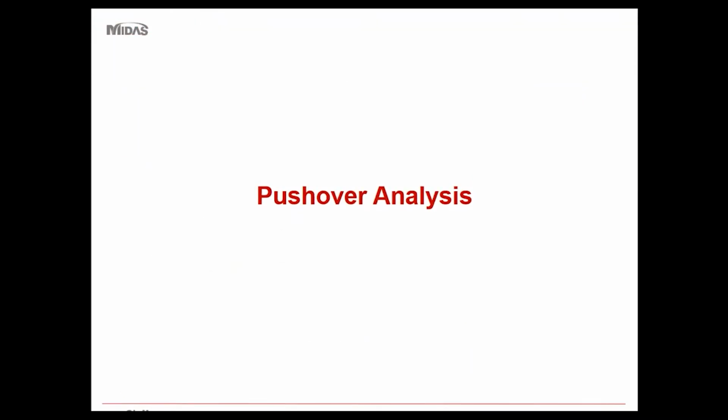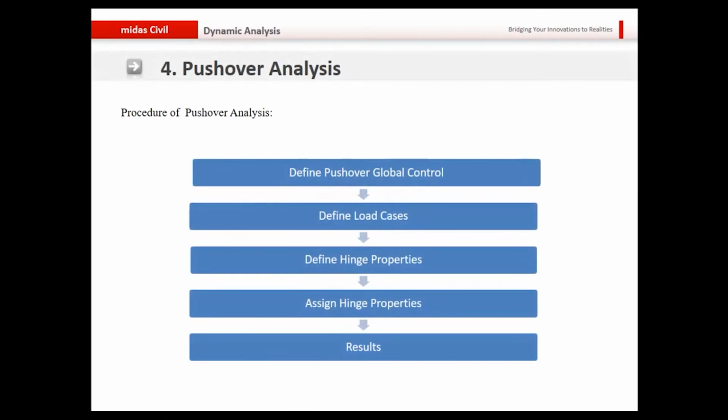Then in the program we have the pushover analysis, which is, as you might know, a static analysis that considers the nonlinearity of the structure. And basically what it does is you apply an incremental lateral load that will generate certain force and deformation on the structure, and then from there you can obtain its behavior, which will be simulated during the earthquake.